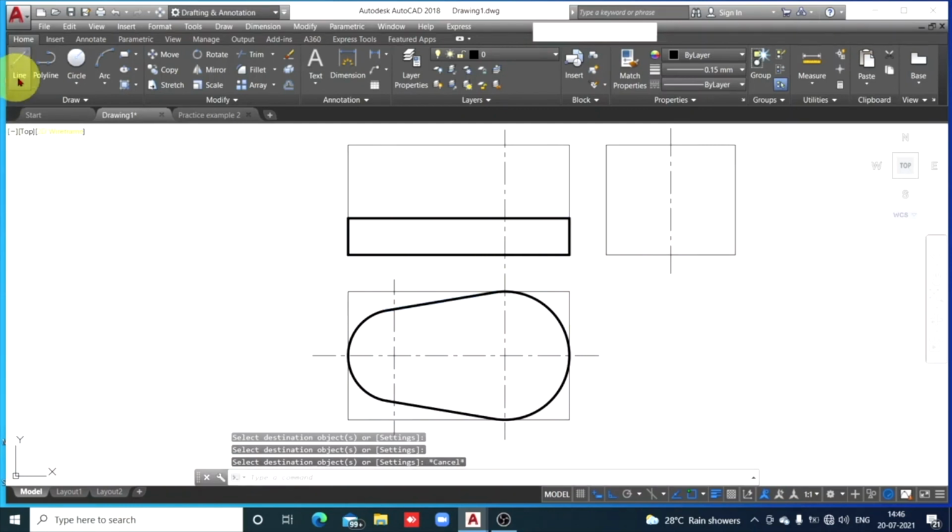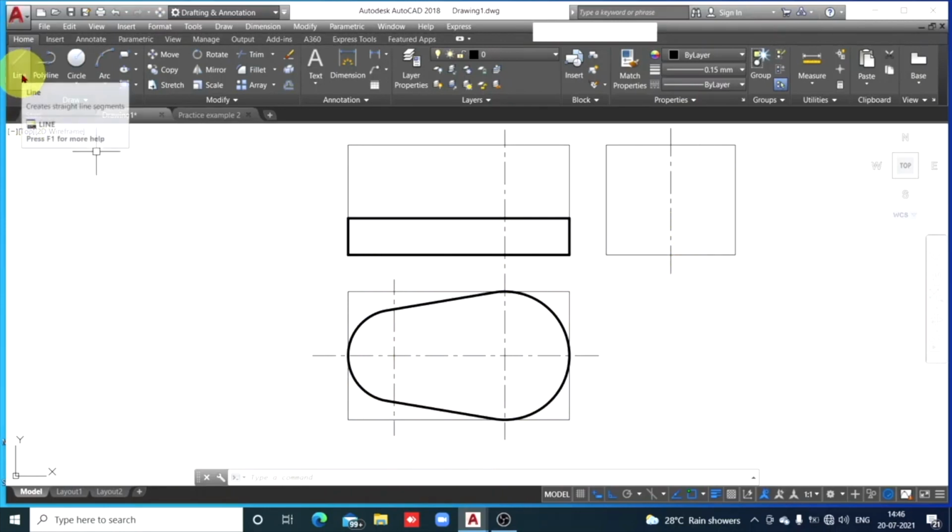Similarly, I'll draw the side view. It is also a rectangle. In the top view it has its shape, and the remaining two views are rectangles. Remember this logic. But what is the width of this plate? The vertical dimension in the top view is the width. It is 70. In the side view the width appears horizontally, and that 70 millimeter width we have already measured in the side view. And the height of this plate is 20. Okay.